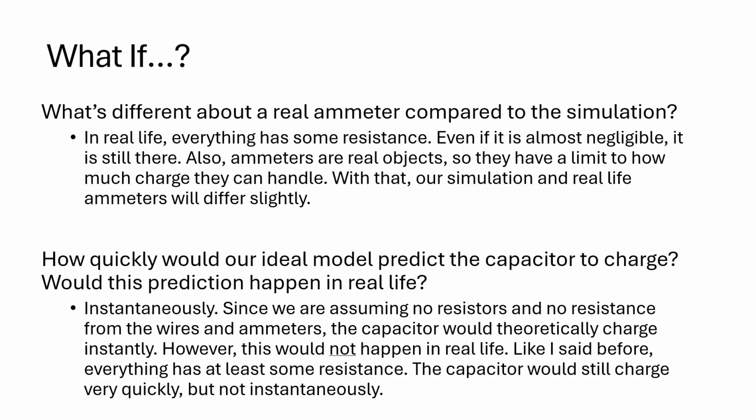How quickly would our ideal model predict the capacitor to charge, and would this prediction happen in real life? So our ideal model would predict the capacitor to charge instantly. This is because in the simulation, it counts the wires and everything else as having zero resistance. With that being said, since there's no resistance, the capacitor would charge instantly.